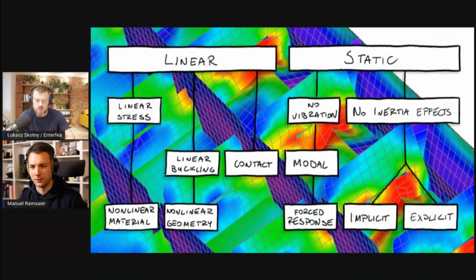So you have difficulty here, I think. With the modal, you just use that if you don't have any idea, or not a very precise idea, of what frequencies your structures will see. And if you know perfectly well that you have this machine emitting this frequency and you have another machine emitting another frequency, then you use the force response to check for those sources of frequencies you have. And so you can also boil down a little bit which model to use. All right. Yeah, that would be perfect.